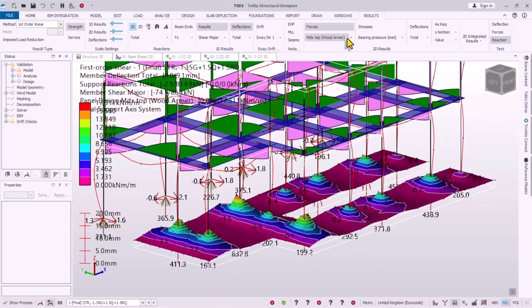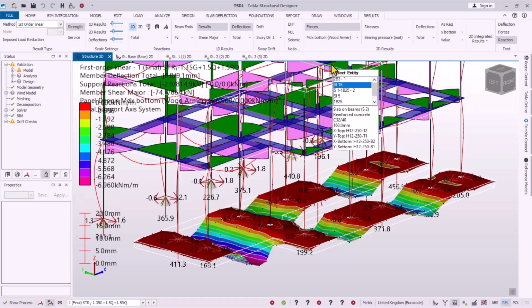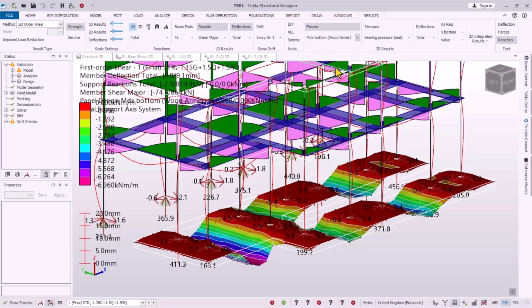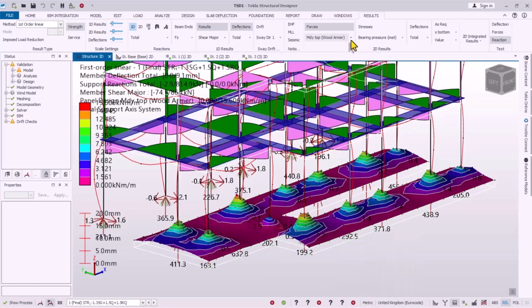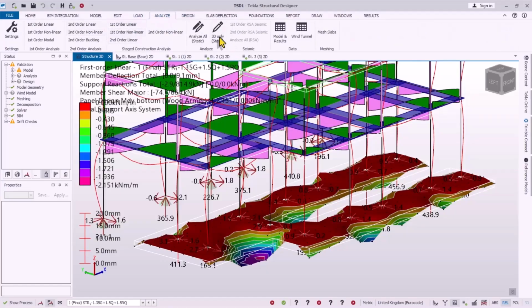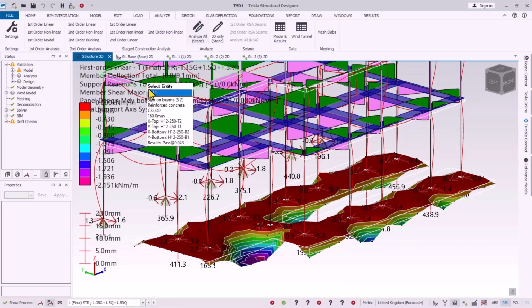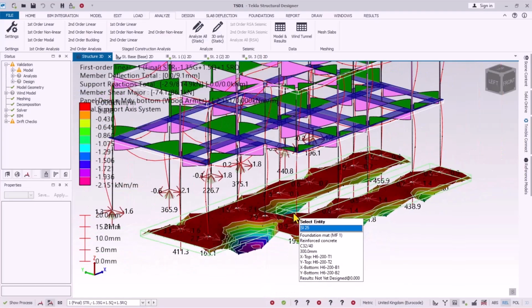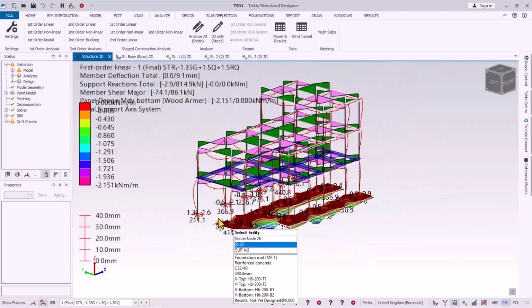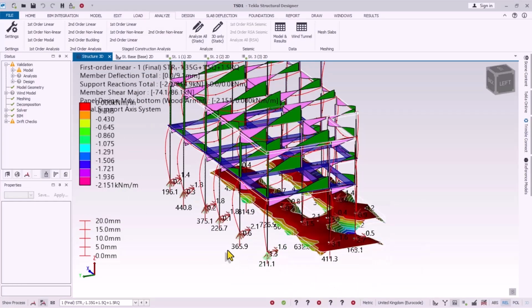And then over here we also have the bottom, using Wood and Armer to also check that. This is similar to what we have in Tekla Structures. All right, you check that also successfully. Go back to the analysis again, and then you carry out this 3D only statics. Click right there, and that has been done successfully on the strip footings. Okay, so having done this analysis, we don't have much to check here. We need to proceed to the design of the strip footings.